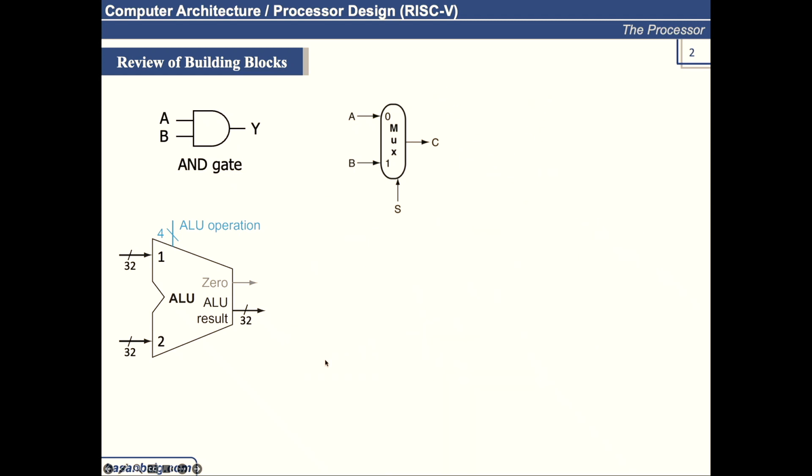Apart from this ALU, we will also be using this component, a simple adder. Whenever you see something like this add, you just assume that whatever is at the input, usually a 32-bit input data at port number 1 and port number 2, whatever we provide, it will be added, and the result is produced at the sum output. We will be using this component separately also.